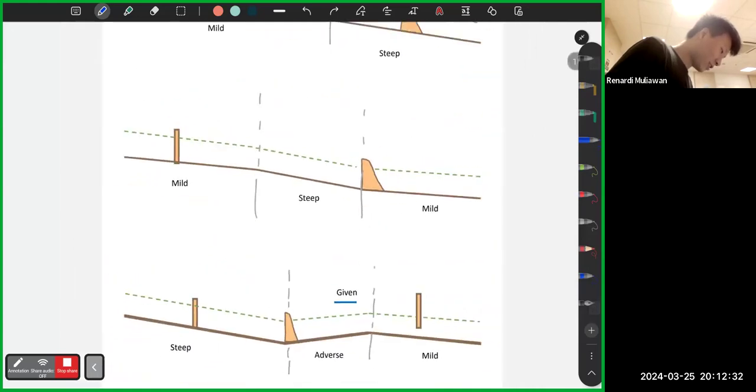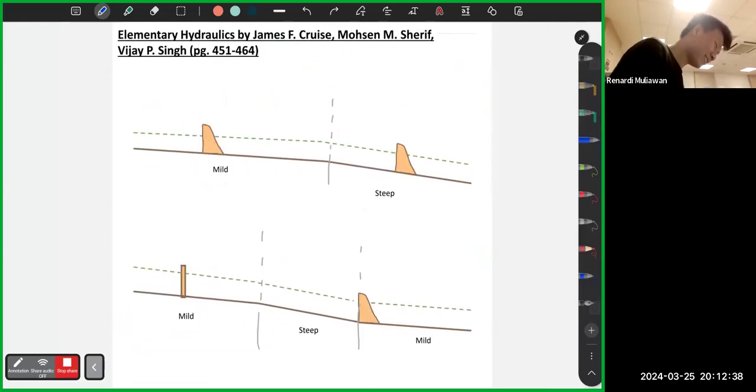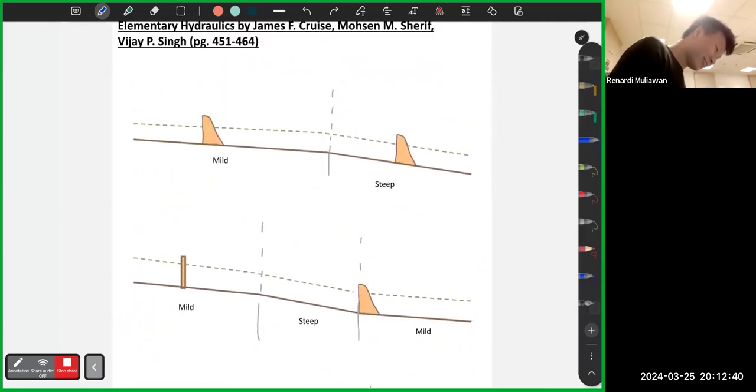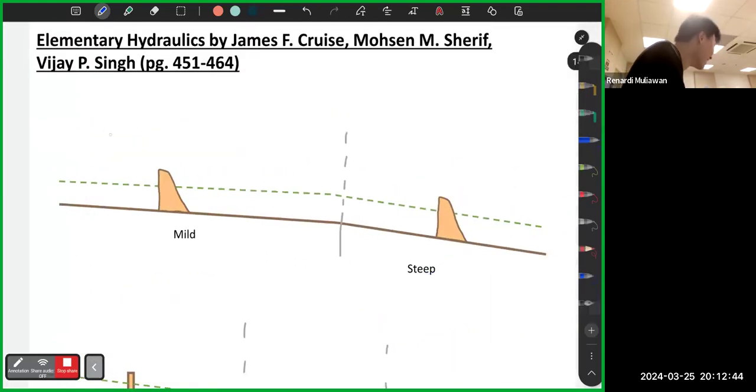Okay, this one you try yourself. I have the answer key, so you can look at it. But it's the same pattern. Okay, let's do just one. You start here, mild, you start up high, above YC. Then this one you can treat as a sluice gate. So again, you need to go up. So here is M1.